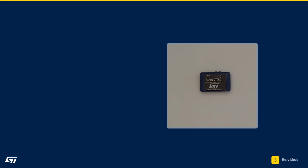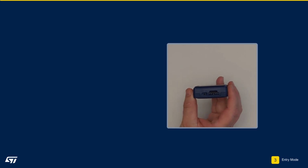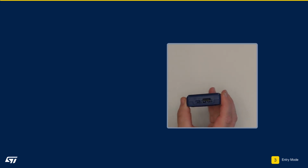First, turn on the SensorTile by using the power switch on the side of the box. Note that your SensorTile does not need to be plugged into your PC via USB, since it can be powered by the onboard 480 mAh battery. If you are turning on your SensorTile for the first time, it should have come with at least a partial charge that should be enough to get you through this portion of the workshop. However, if your board does not power on, it's possible the battery does not have enough charge. In this case, please connect your board to your PC using a USB Type-C cable.